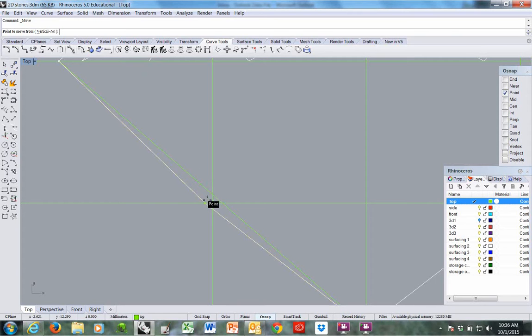You see how my marker departs from my cursor to grab it. So now I have exactly that point. I'm going to right click on near snap, and I'll just slide it along this curve until I get a nice hip or bump there. That's fine. I'll hit F11 to turn off the point.